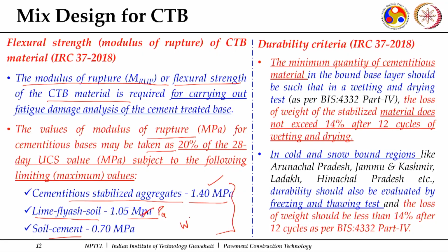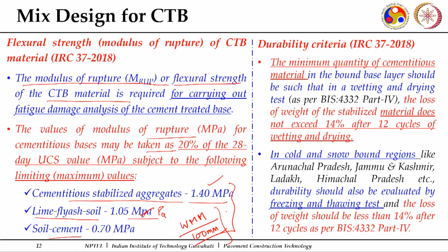That crack relief layer can be in terms of wet mix macadam. 100 mm of wet mix macadam layer can be provided as a crack relief layer, and the wet mix macadam gradation we already discussed. This aggregate interlayer is preferably provided over the cement treated base, and in this case it is usually compacted to 100% of its density, which is your laboratory derived MDD.